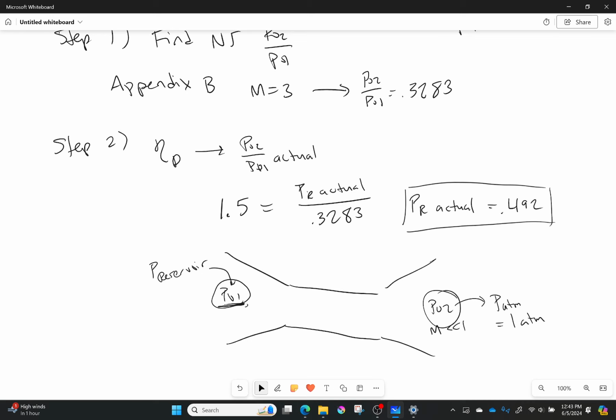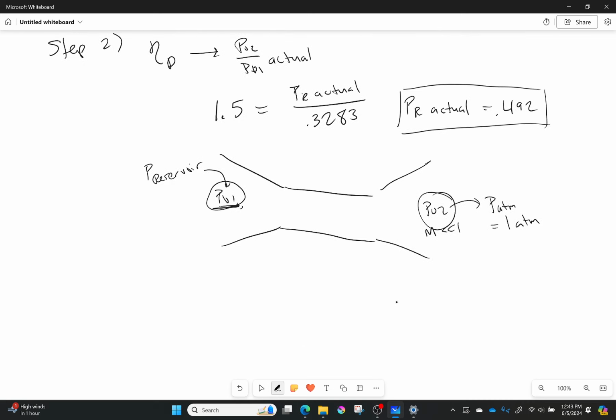If you're not understanding how I'm getting that, just think about it this way. Your static pressure has to be equal to atmospheric at the end. Otherwise, you're going to have something happen. It's either going to lead to an expansion fan if it's more, or a shock wave if it's less, at least in the case where we were going supersonic. We should be moving subsonic here, so I guess that honestly wouldn't matter.